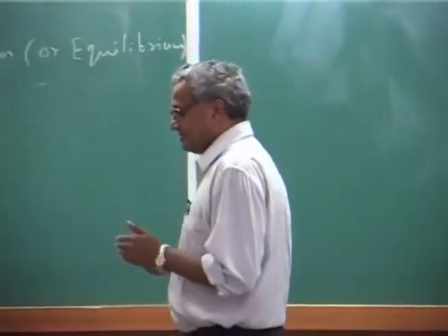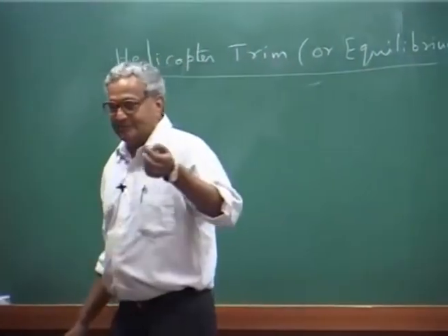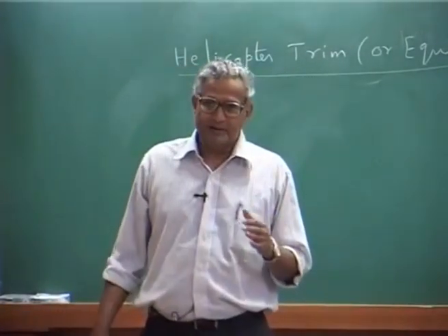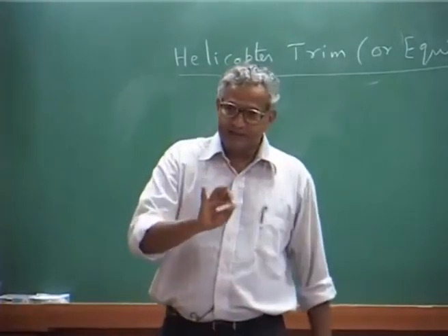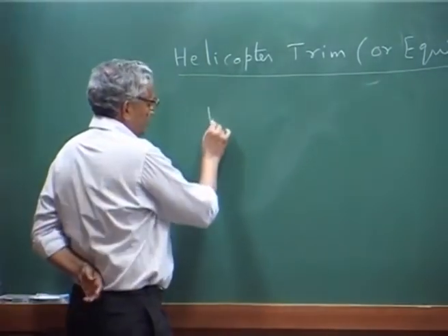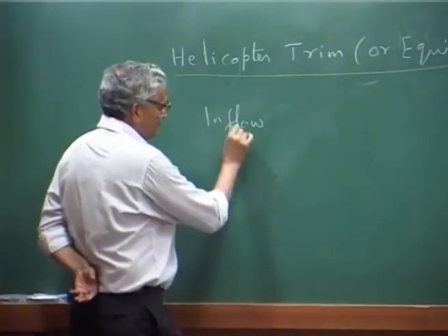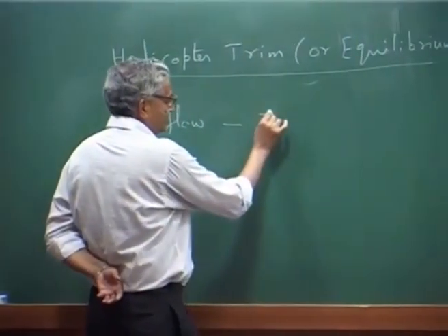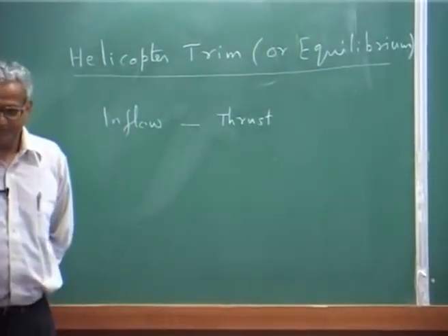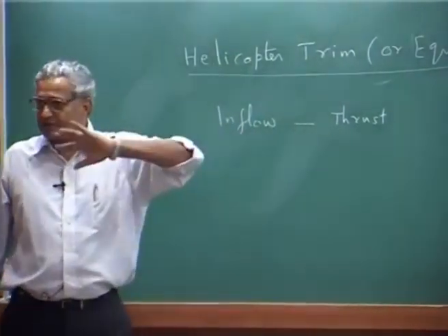Now, for that, pilot input will be evaluated theoretically. How will you get the trim from what we have learnt till now? Because we have learnt inflow first, and then inflow was related to thrust. Okay, this is one equation, rotor inflow. Of course, thrust is the key. You have forward flight condition, attitude, everything is there.